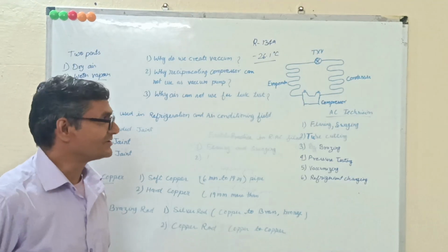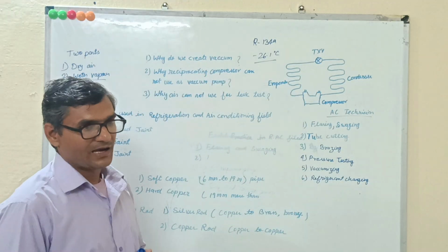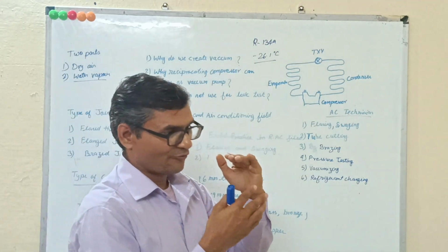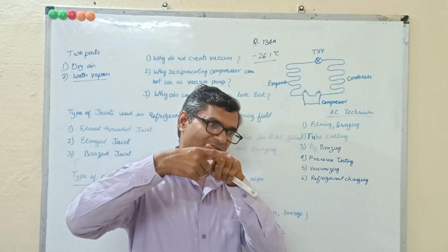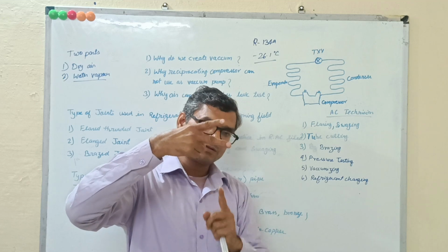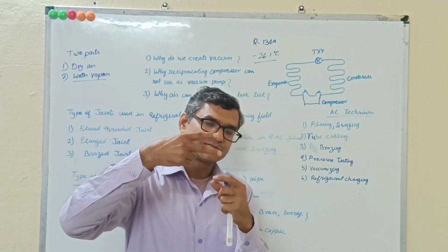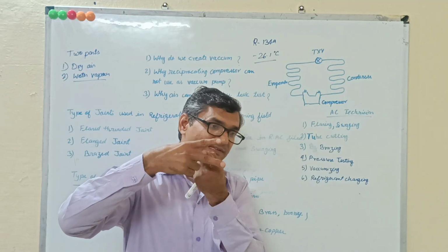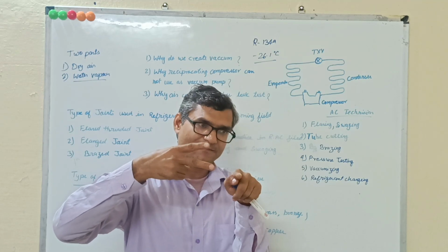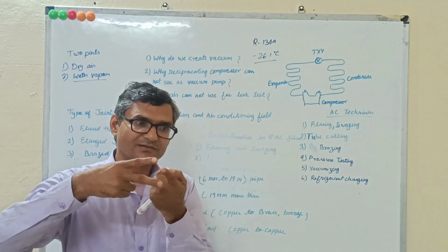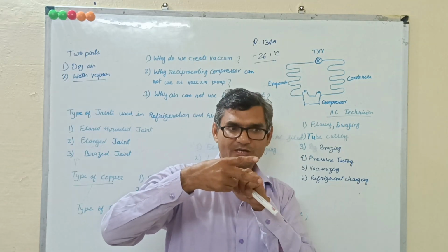Because, as in the previous video, a reciprocating compressor has a valve plate. The piston going up cannot directly strike it, so to avoid a strike, a gasket is provided, and then some clearance will be there. That clearance is called the clearance volume.